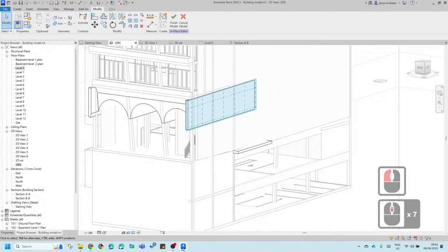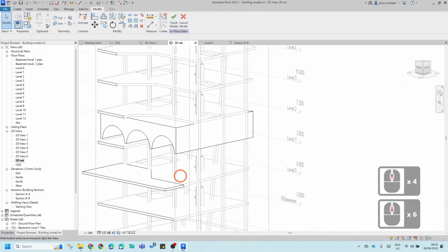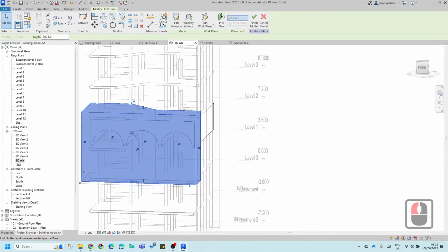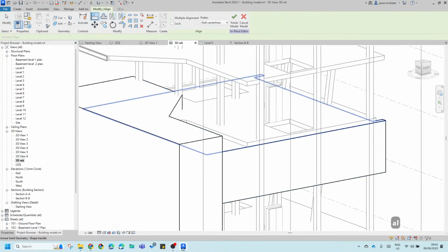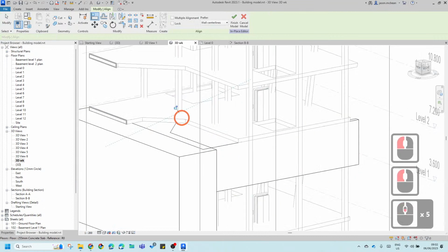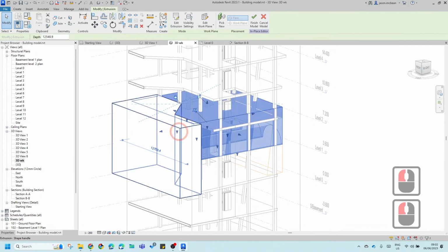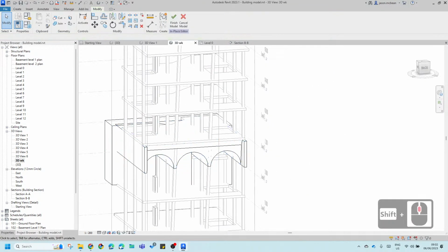3D view. So this working view is that view that we used the whole time. And maybe what you do is you then focus. So here's that extrusion. So here you can say, well, actually that must just cut away that. And what is neat is you can use the lock and align tool the whole time. You can lock these together. So if this extrusion actually goes thicker, you see what it does. That moves with it. So if it's cutting it, it'll always cut it out perfectly.